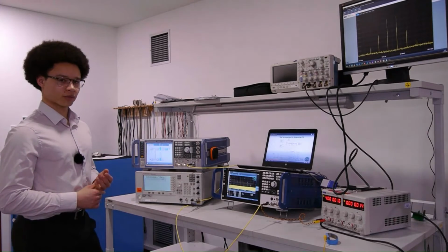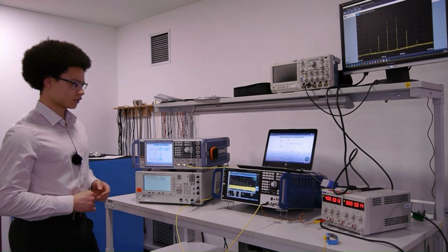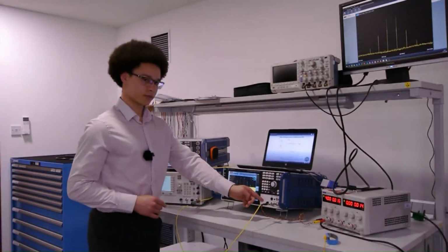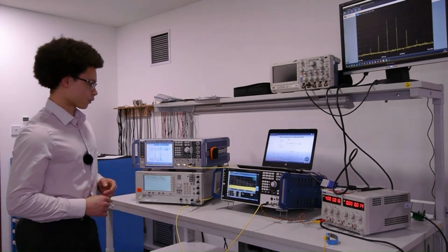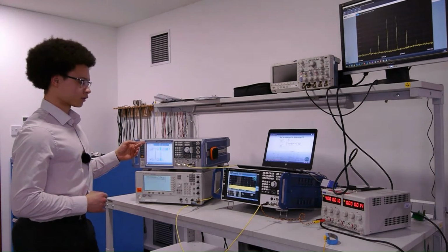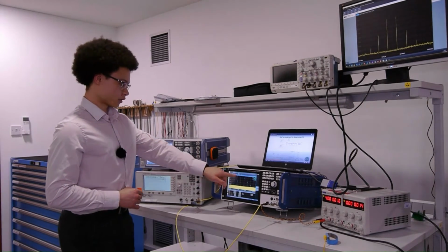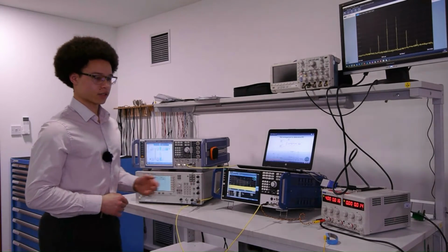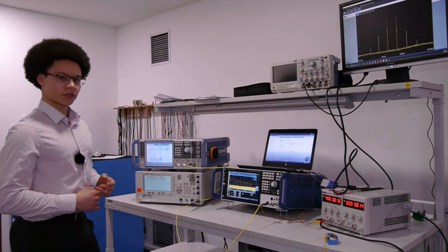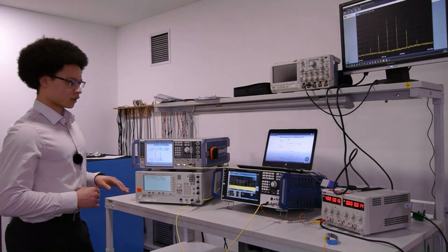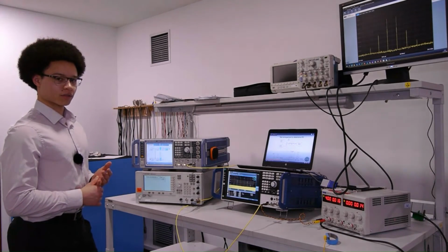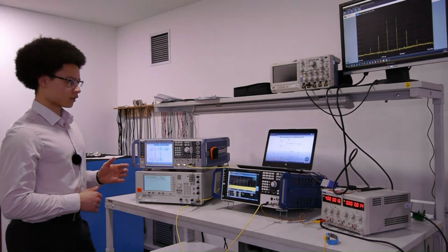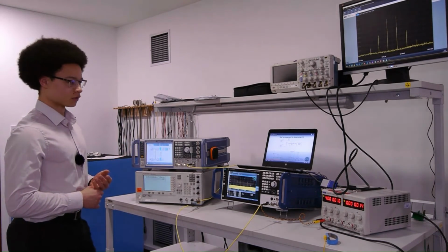Before we start the main measurement routine, there are a few things that we need to do. We need to measure the loss of the components between the DUT and the spectrum analyzer, and we need to determine what powers to set the signal generators to, so that the output tones have the same magnitude at the spectrum analyzer. It's also a good idea to take a few manual measurements before starting the automated routine to make sure there are no problems with any of the test equipment and the setup, or with your measurement program itself.